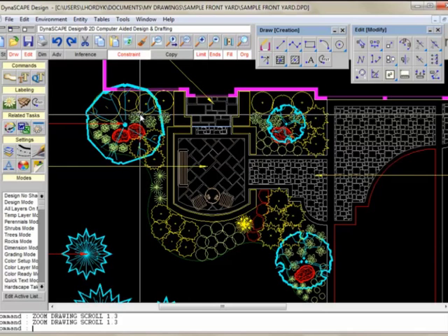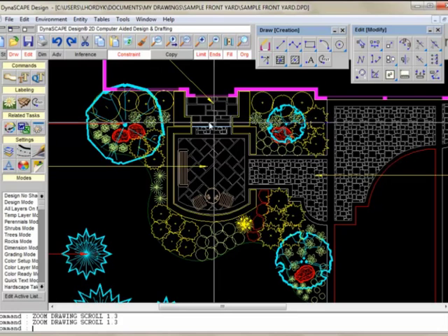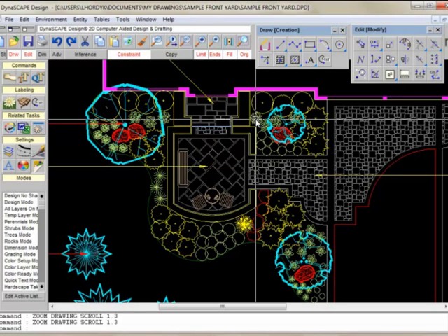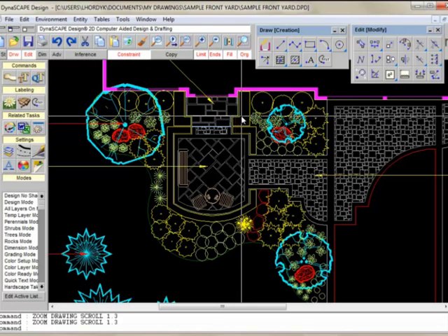You also have to have unique symbols. For example, at the top here I've got these three plants. These symbols are exactly the same as these three here. When I go to swap them in Google SketchUp, it will replace all these plants at the exact same time. So if I wanted these to be different from these, I should use a unique symbol for that plant.